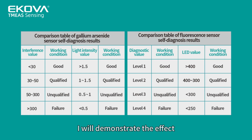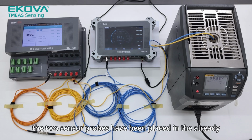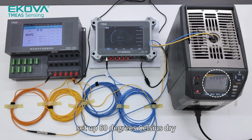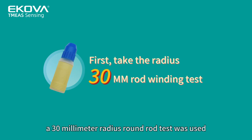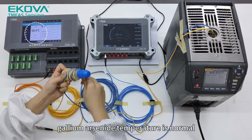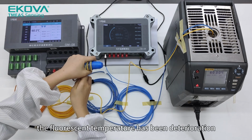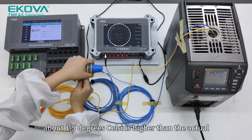Next, I will demonstrate the effect of the bending radius on the performance of both sensors, as well as the diagnostic effect of the self-diagnostic value. Prior to the start, the 2 sensor probes have been placed in the already set up 60 degrees Celsius dry well furnace. First, a 30 mm radius round rod test was used. At this bending radius, the gallium arsenide temperature is normal. The fluorescence temperature has deteriorated, about 1.5 degrees Celsius higher than the actual.